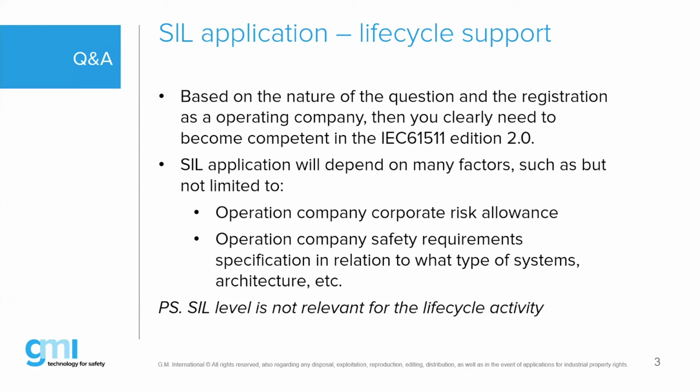Your corporate management will have to tell you what is a tolerable level in your production units, and that's a given fact by them. And based on whoever has done, or which department has done, the investigation for the hazard and risk analysis, based on that outcome, you will need to decide how much SIL level risk reduction you may need.